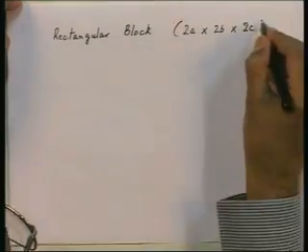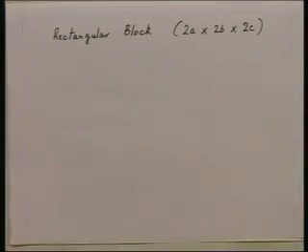It is initially at a uniform temperature T naught. I put it in surroundings at a temperature T f. The heat transfer coefficient on all the 6 faces of this block is h. Find the temperature at any point in this block as a function of time. Now, T is going to be a function of x, y, z and time.